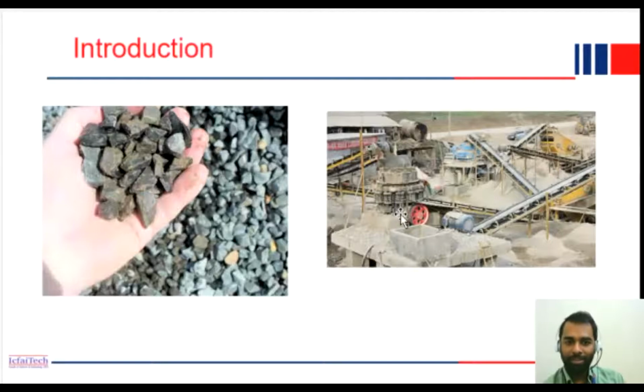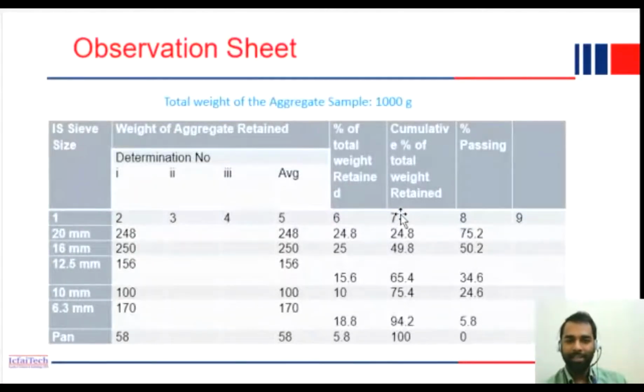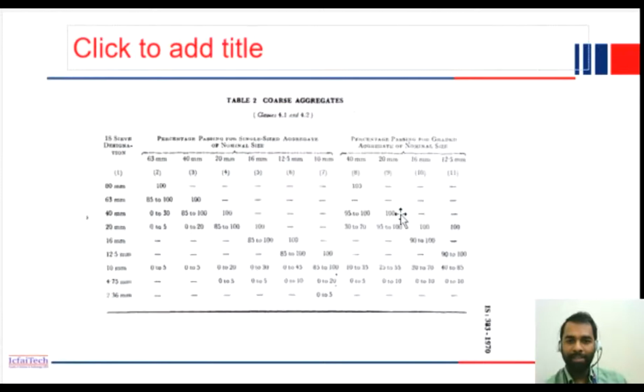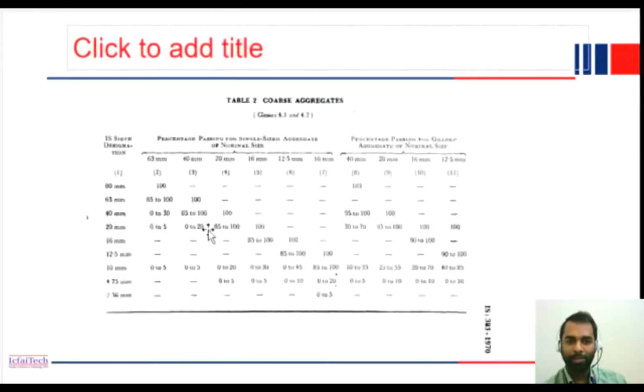Okay, so in this sieve analysis method, we are finding out the nominal diameter size of the grade. Then we tabulated all these values, and then we got what the size is. Then we verify whatever value we get with this IS code table. This table is a standard table, in IS 383. So all the values will be there. For example, if the nominal size of aggregate is 16 mm, then you should get this column.